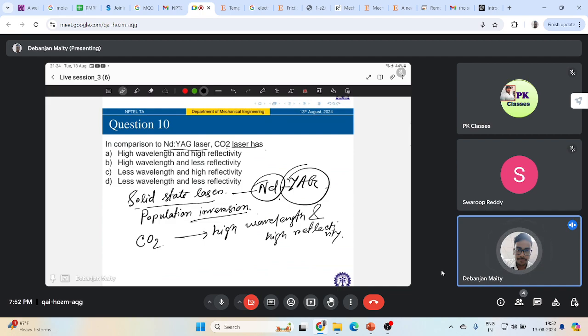There is surface modification, such as roughening operation, oxidizing operation, and some kind of coating can also reduce this reflectivity. Then also there are shielding gases to protect your molten metal.